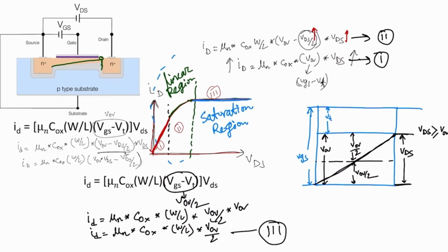So this is the whole concept of the MOSFET current, how the channel is formed, how the channel is tapered, and what the value of the current is in the saturation region. In the saturation region, the channel is pinched off, but the current is not zero. Keep that in mind. So we need to find the voltage or current with this diagram.